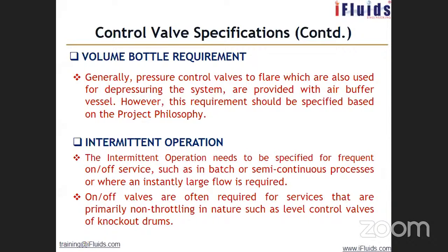Once you flush the toilet, the water level goes down, the ball comes down, that opens the valve and water comes into the flush tank. Once it is filled up to the top level, the ball will rise and close the inlet valve. This is automatic level control. It's the simplest example I can give you.